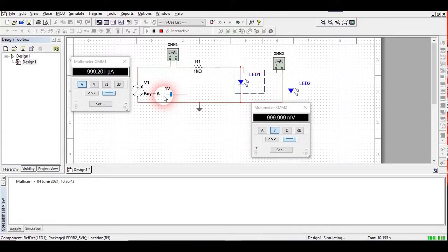I'm going to increase the voltage again. So after 1 volt, we are seeing that the current comes in nano ampere. The current is in nano ampere only. It is around 2 nano ampere at 2 volt. So in the DC characteristic, we have seen that after around 2.6, 2.7 volt, the graph sharply increases.